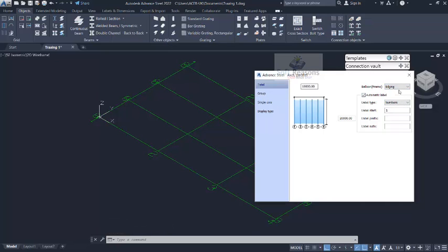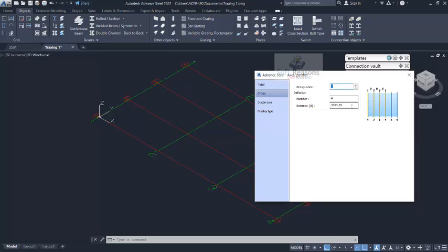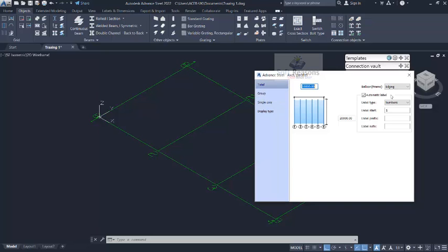Okay, so after which you proceed to the group right there. So you can see we have 4 numbers of grid lines right there, but I needed only 2 right there, so I can key in 2 right there. Click on this provision to have it at 10 meters interval right there. Okay, so the setting here is done successfully.